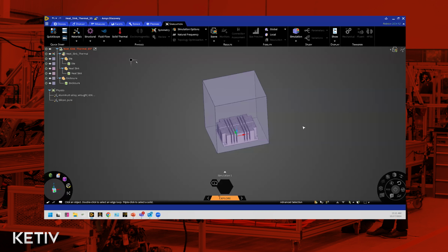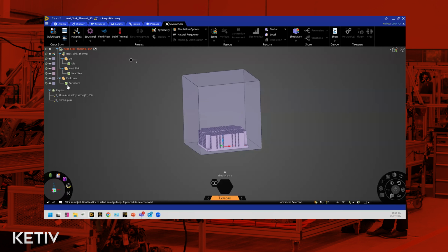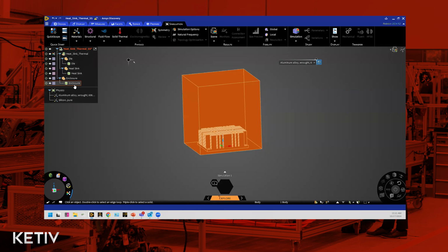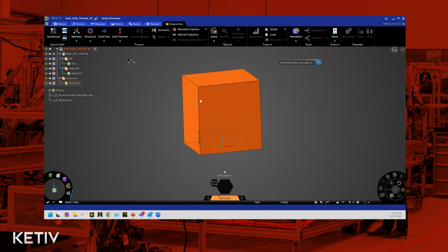Let's go ahead and fix the fluid property. So I can click on Enclosure. And on the right over here, you see the material. So I'm going to go ahead and change that from here. By the way, you don't need to specifically choose this from the structure tree. You could also just triple click on a geometry to select the entire volume.